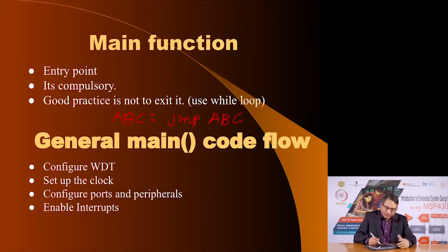Well, what we do in the context of MSP430 is that we will cover this. This is a watchdog timer. It is a very important feature of any microcontroller and you need to configure it. So, you can choose to have it operational or you can choose to disable it, but you must deal with it.